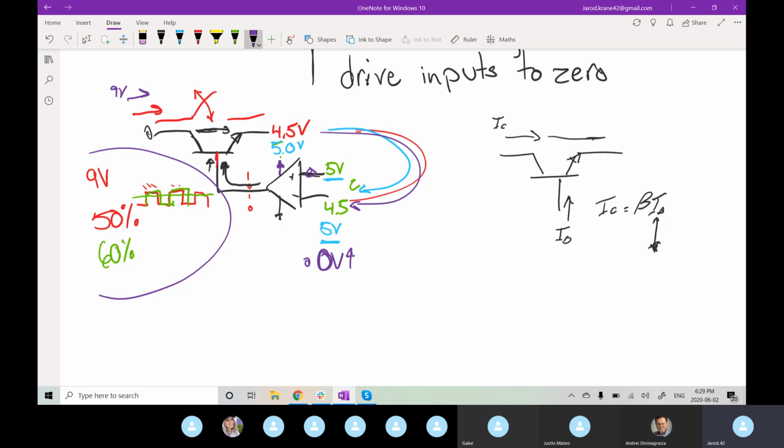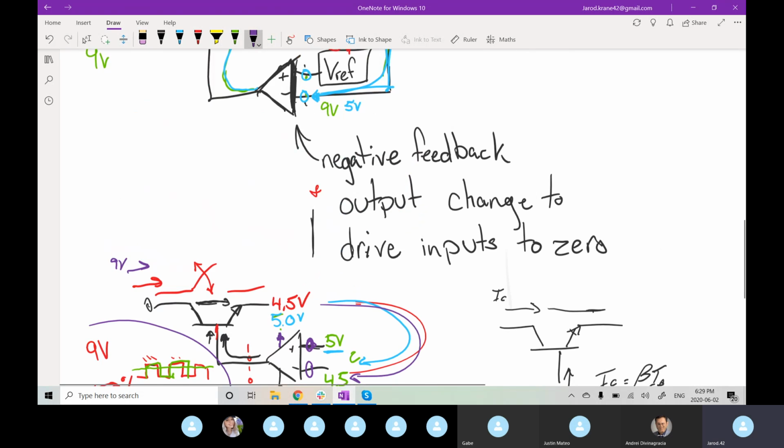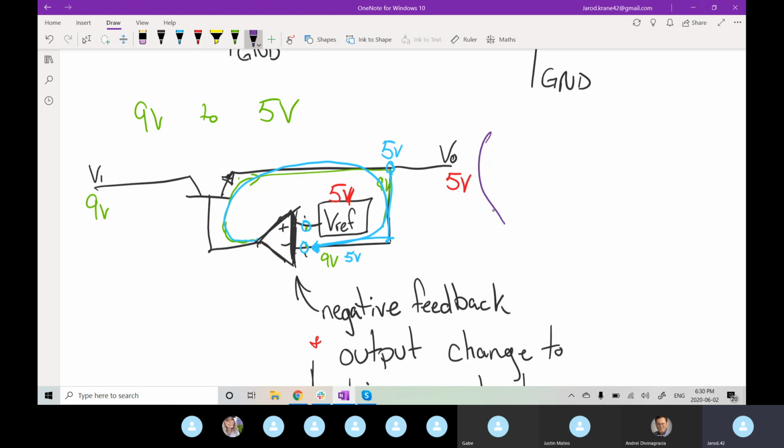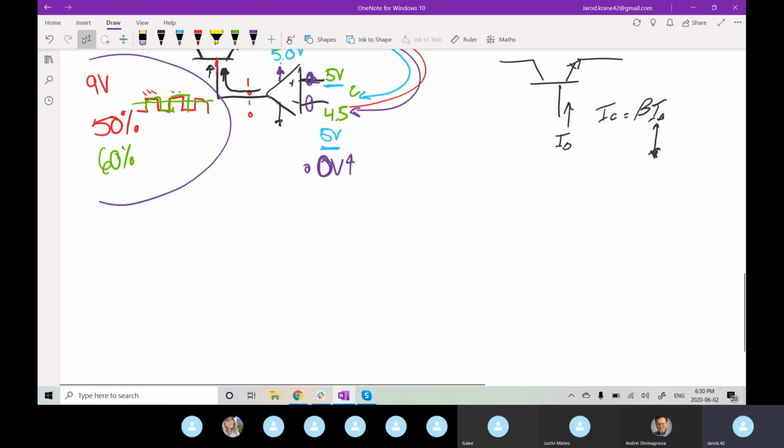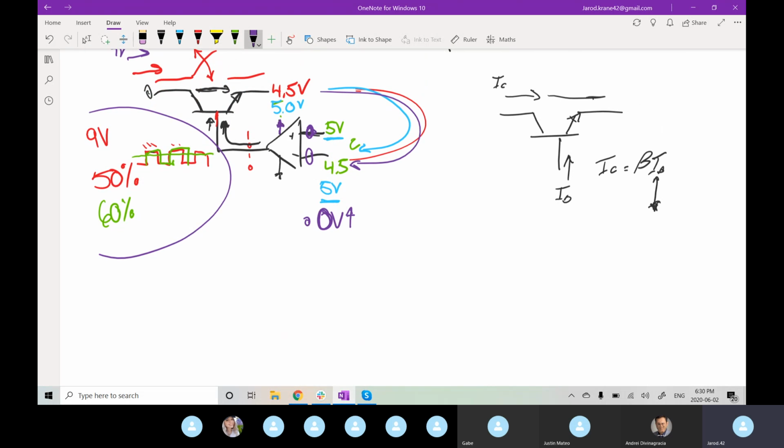But as soon as your op amp is active, it already sees a difference between your positive pin, which has a steady 5-volt reference, typically built internally into the linear regulator, and your negative pin, which would be sitting at 0 volts, or whatever voltage may already be attached to your output, most likely none. So it would just be sitting at 0. So it wants to already start trying to pull those pins together.